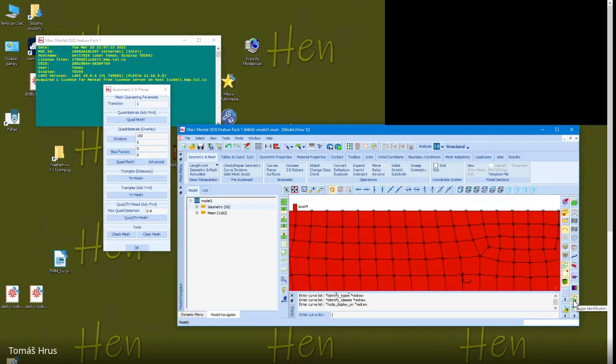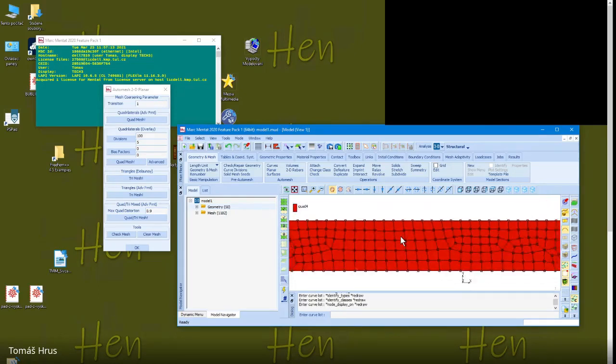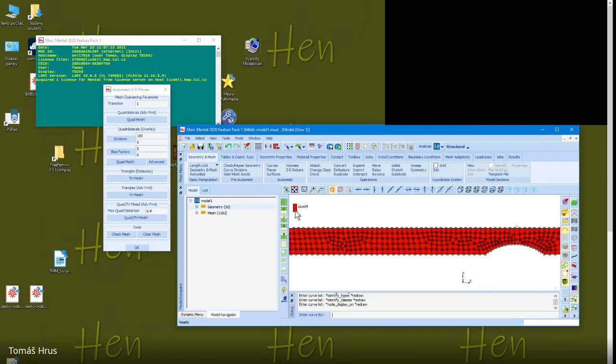Again, from the geometry, it's known that this is a so-called linear element because it has 4 nodes, 1, 2, 3, 4. Each element has 4 nodes. For the quality of results, it's much better to use quadratic elements. So now it's quite useful to change our mesh, which is composed of linear elements, to quadratic elements. Here on the operations on the top, we have change class.